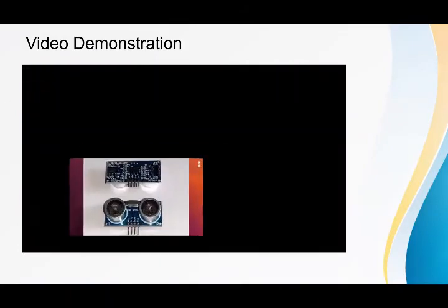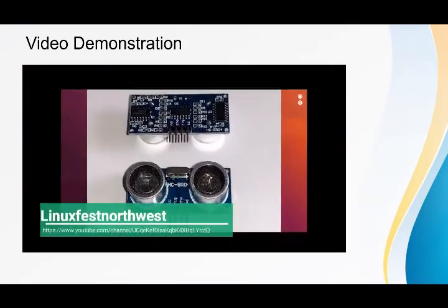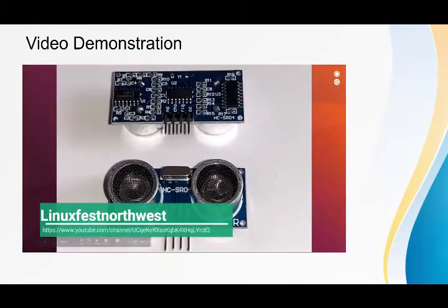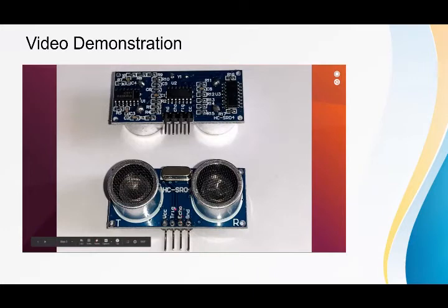The microphone essentially over here. All right, so this sends and this receives, and then shortly after the trigger is set high, the pulse is sent out, and when it's sent out, the echo goes high and echo stays high until it's received back. So you'll see that emulated in the code.